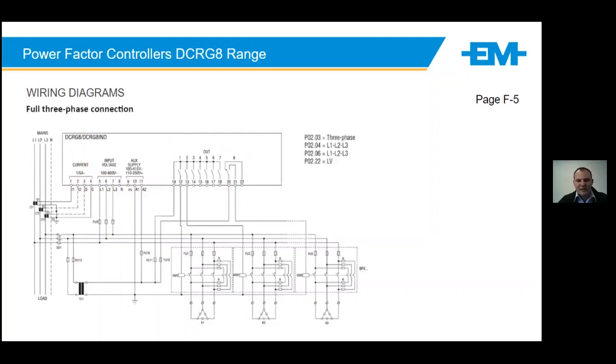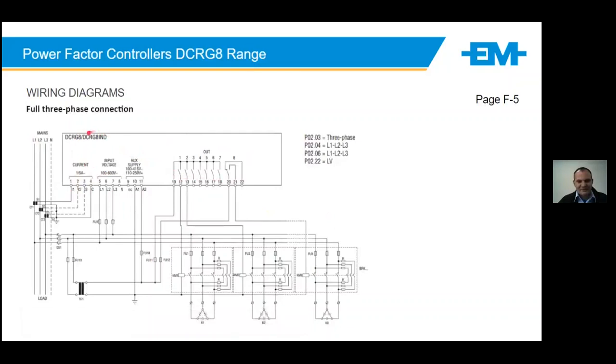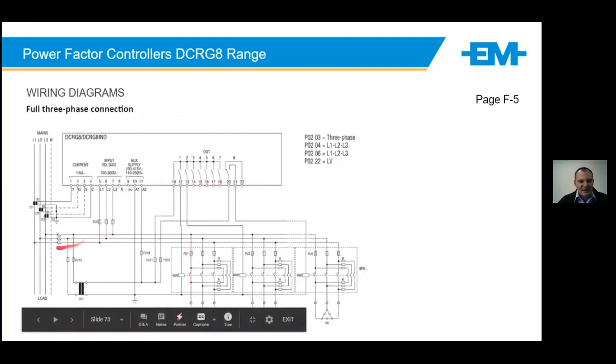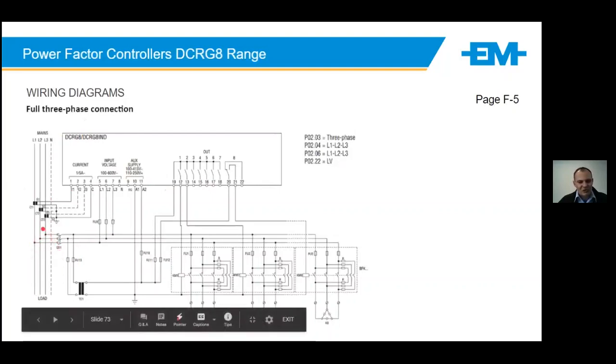It can also be a kilowatt hour meter. Obviously, it's not for your billing purposes, but it is there to give that data. In our example, we have here just up to 8 connection methods through relays to the capacitor banks. Okay, so total site is being measured, controller makes a decision, and it brings in the required reactive power to compensate for the total load.